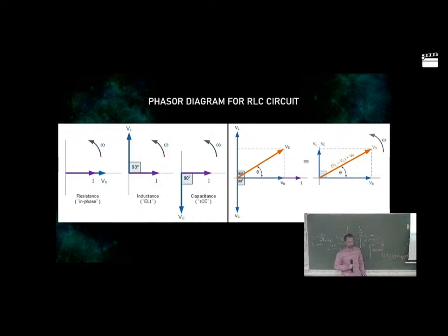It shows that the inductor is not allowing sudden change of current. Similarly, for the capacitor we write Vc(0-) = Vc(0+). So it shows that the capacitor does not allow sudden change of voltage. Are you getting my point?